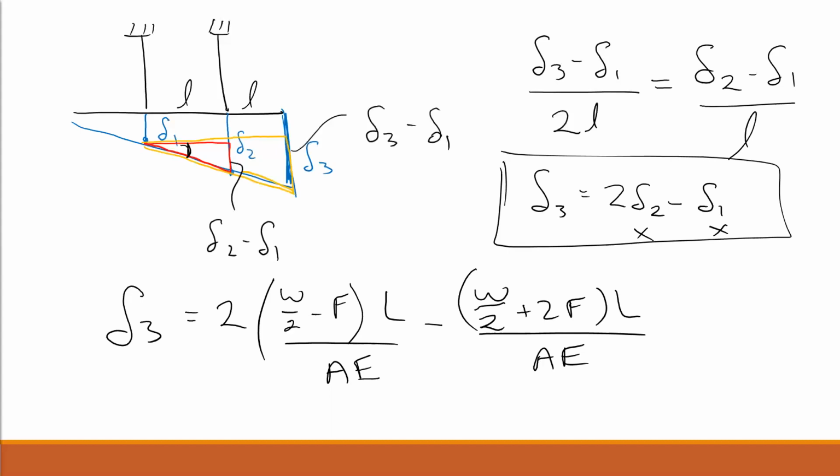Yes. So if we go from R1 being tension to R1 being compression, so if this is, say, a rope and you try to put that into compression, you now have nothing to resist that. And so now you're going to tip your platform over, right? That would be where you become unstable. And that's related to the rotation. If you get enough rotation, it no longer is tension and it starts to want to be compression.